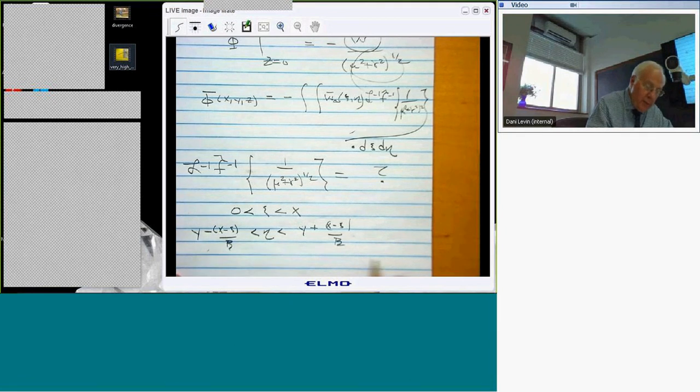And beta is this magic factor, the square root of the Mach number squared minus 1. By the way, in subsonic flow, the same factor will appear, except it will be 1 minus the Mach number squared, right? I mean, after all, in supersonic flow, this is a positive number, and in subsonic flow, this is the imaginary number. So this solution can't possibly work there.